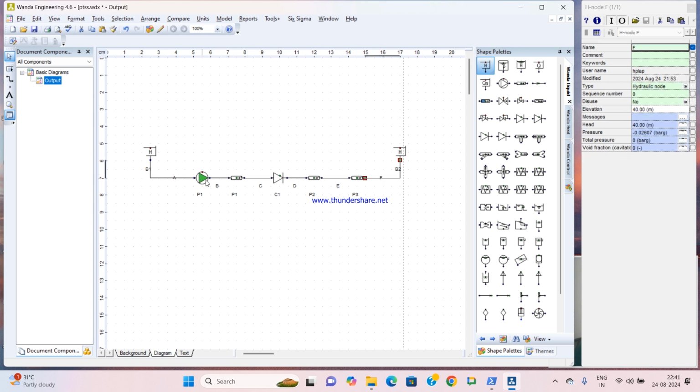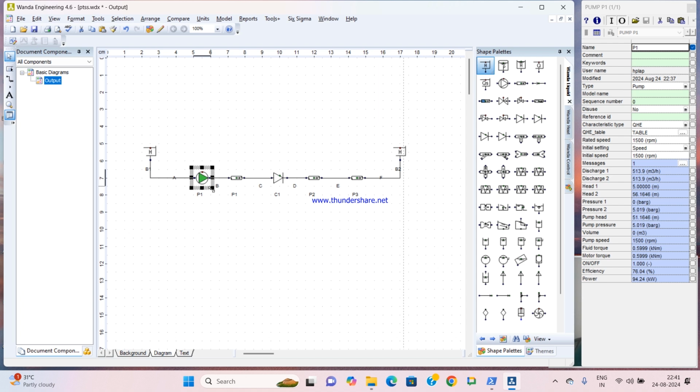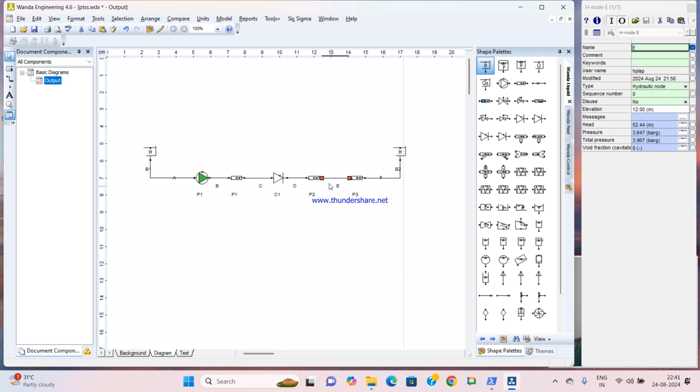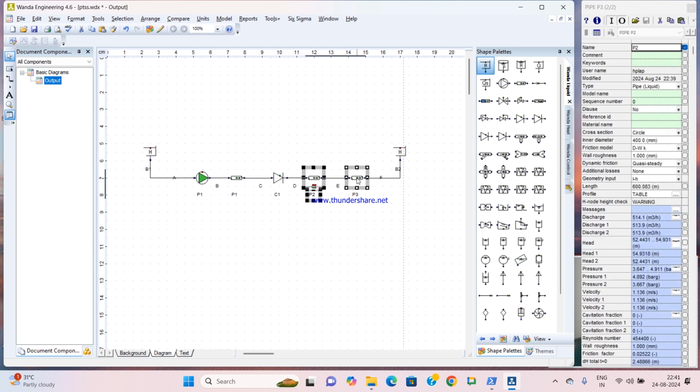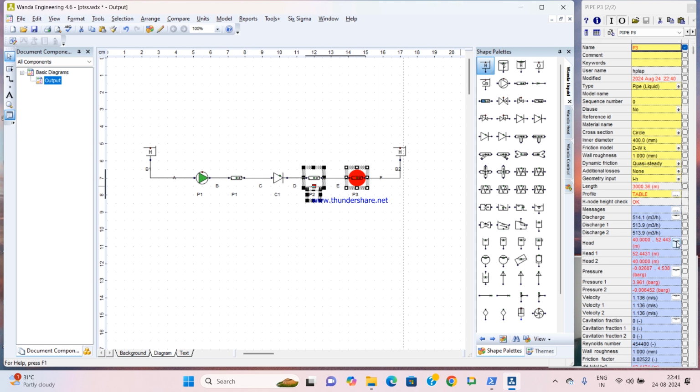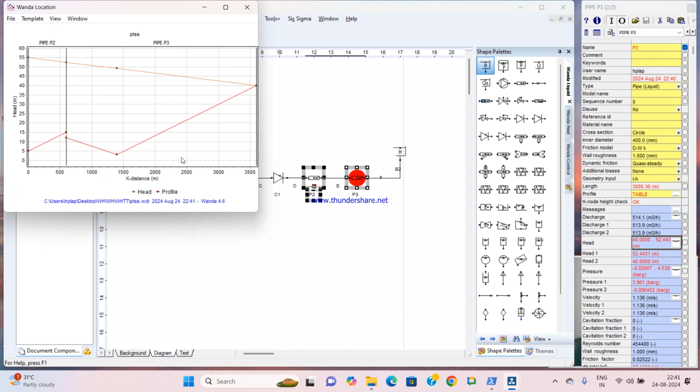So what will happen if this pump is suddenly tripped? There will be backflow, and there is a check valve. So normally in this portion some transient will occur, but this portion is for the steady state. I am showing the steady state. Now if you do the steady state calculation, and see the total head in this pipeline, you can see this kind of thing.